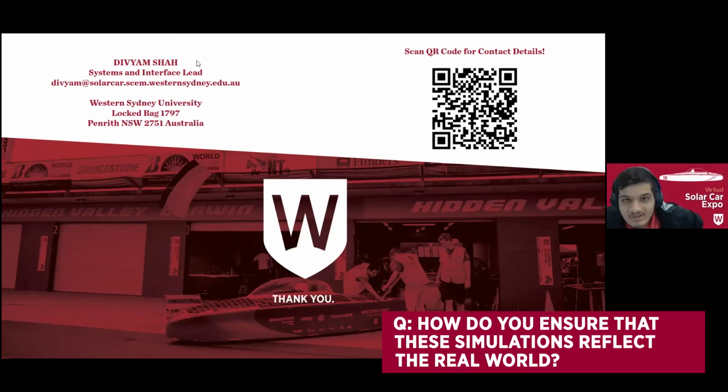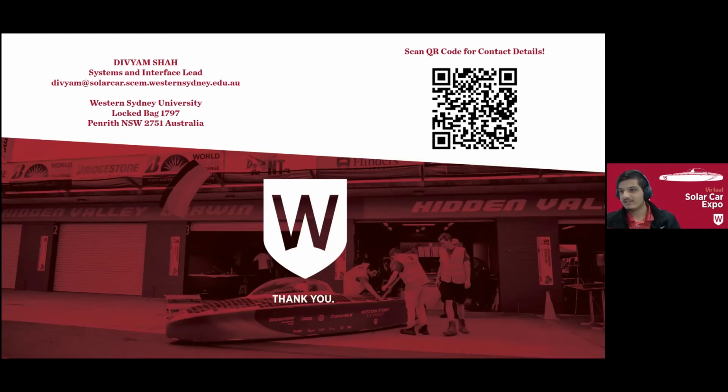No, that is a great question, and it's something that we need to make sure that we're on top of almost all the time. And it's especially hard for things like composite simulations, where it's so dependent on the mathematical model, the material data that you're able to provide to the model, and so forth. So what we try to do is calibrate our analysis using some parts that we test destructively. So if there is a representative component for composites, it could just be something as simple as a composite plate.